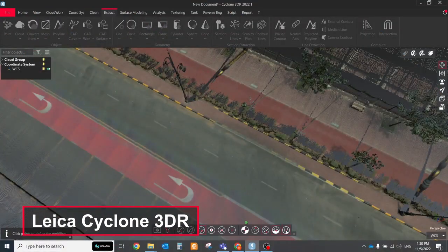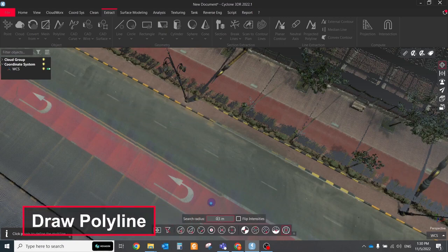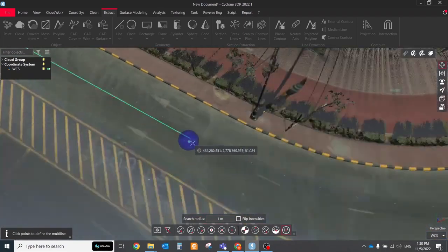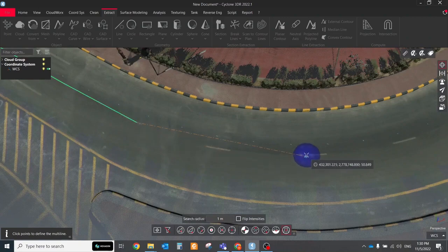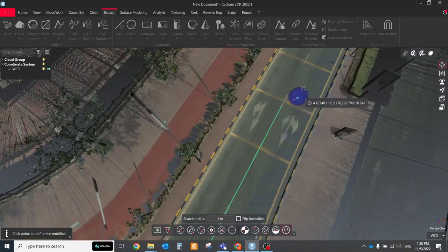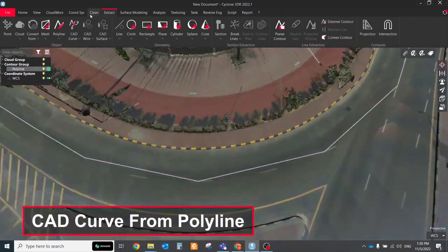For that task we can use manual and automatic approaches. For manual creation of polylines, select the Draw Polyline tool and choose the snapping mode to white line. The polyline will be created at the axis of white line thanks to a seed point. You have to enter a search radius, buffer area where the software will recognize white lines. If your polyline contains too low number of points for an accurate representation of the curved lines, you can try to convert it to a spline.